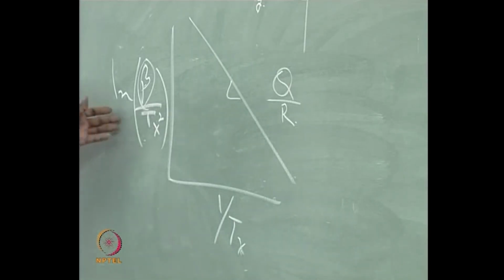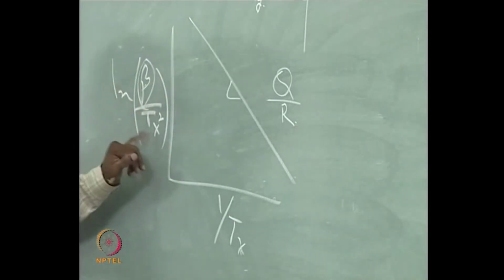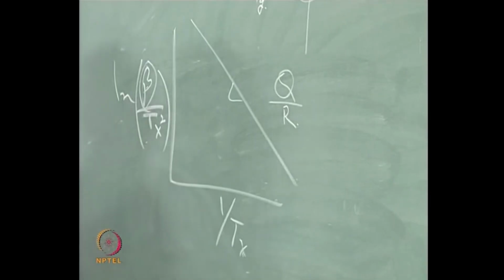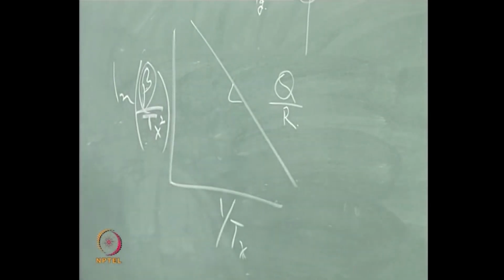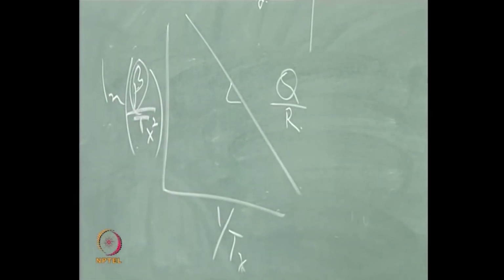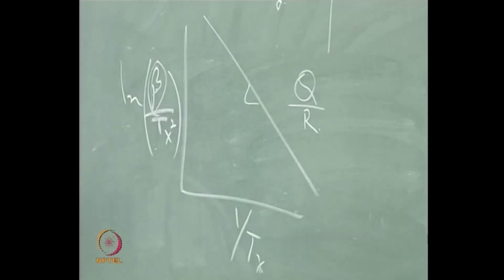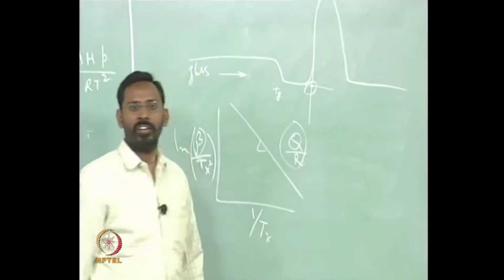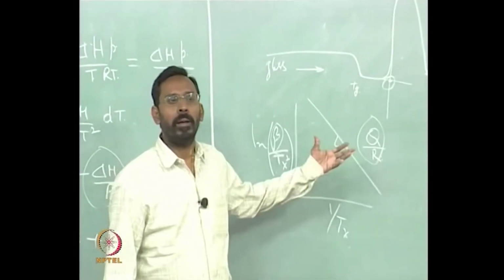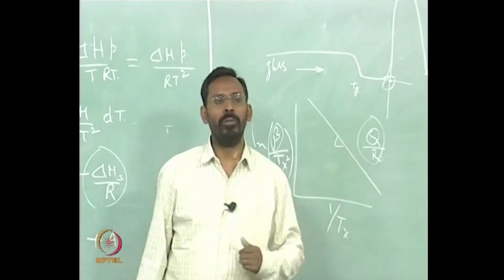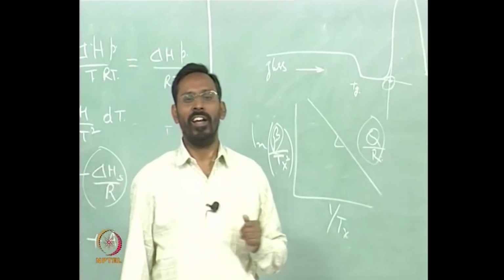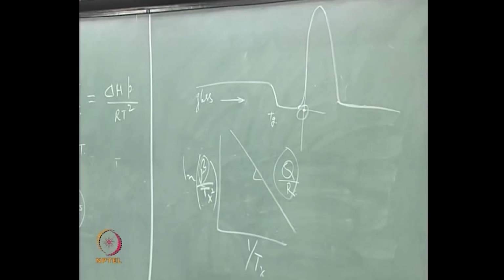Similarly here you simply take the beta and Tx and tabulate them at least for 4 or 5 different heating rates, because to get a consistent plot you do a least squares fitting. This is how, for any such reaction, whether it is a polymorphous transformation, an allotropic transition, a crystallization of a glass, precipitation or any other transformation, you can use this.